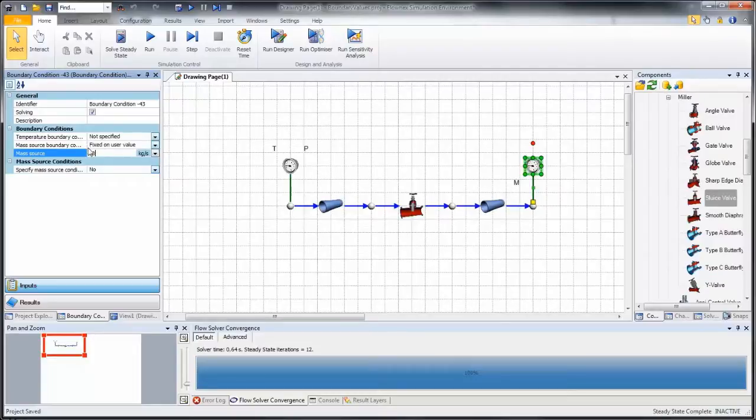Let's go over to the temperature specification. Do you think it is necessary to specify the temperature at the outlet boundary value? Quickly think about that. Well, actually not. Flownex operates through conservation of mass, momentum, and energy. What this means for the temperature is that the amount of energy is maintained in the direction of flow until heat is added or discarded.